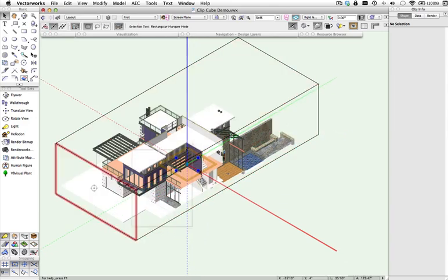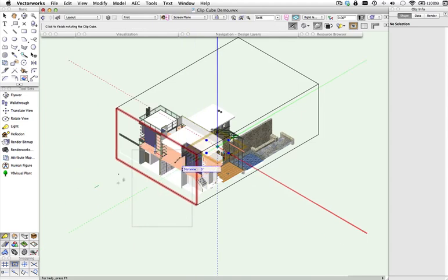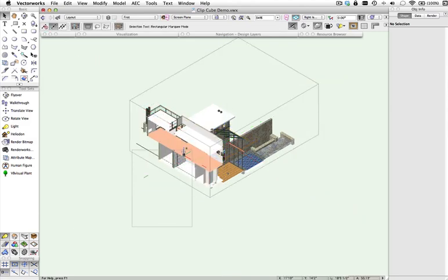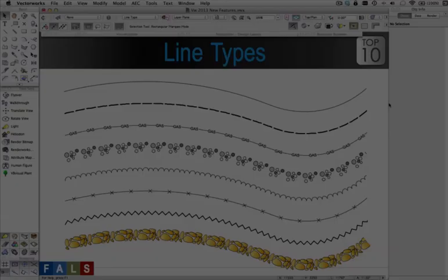Once you've drilled down to a particular area, then everything just works as it normally would. You can select and modify the objects within that area and carry on with the editing. You'll see here I can now select some objects in here, select the floor, and so on.